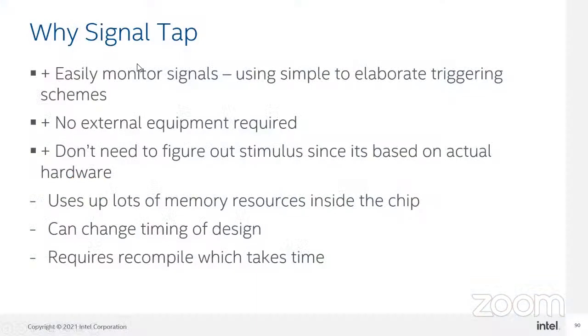Why Signal Tap? The advantage of Signal Tap is that it easily monitors signals using simple to elaborate triggering schemes, and no external equipment is required. We are not going to use any external equipment, no probes. You don't need to figure out stimulus since it is based on the actual hardware. You don't need to pass any stimulus because we are going to see what is happening on the actual hardware. That is the greatest advantage of using the Signal Tap logic analyzer.